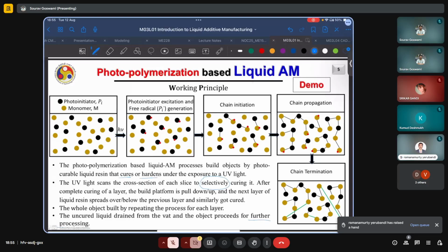In some simple machines, you might not even have multiple lasers, so you need to print both the build region and the support region with the same laser at the same spot size, even the same power. That is why we do not cure the polymer fully.